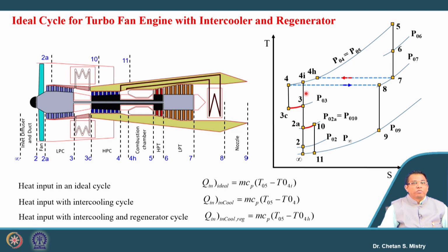This logic was earlier used for land-based power plants. Later on, people started exploring it for application in aero engines. Do not get confused between the terms regenerator and reheating. This regenerator is a heat exchange device where we are regenerating the heat that is supplied to the combustion chamber. If I consider a reheater, then the afterburner is called a reheater because we are heating our gas again. That's the reason why it is called a reheater.